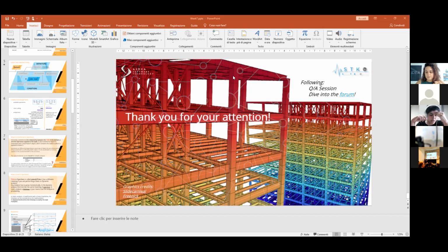Okay. So every time I have 2 stages, I have to put the load constant? Well, it depends what you want to do. For example, in a pushover, it makes sense that the structure is still subject to the vertical load and then moves horizontally. But if you're doing 2 vertical analyses and you want to see the result of your structure to different vertical loads, you don't need to put the load constant.